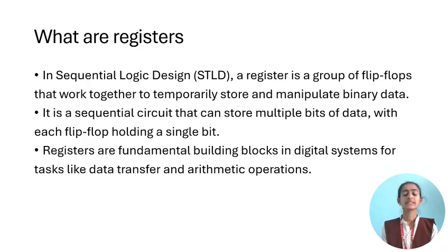What are registers? In sequential logic design, a register is a group of flip-flops that work together to temporarily store and manipulate binary data. It is a sequential circuit that can store multiple bits of data, with each flip-flop holding a single bit. Registers are fundamental building blocks in digital systems for tasks like data transfer and arithmetic operations.